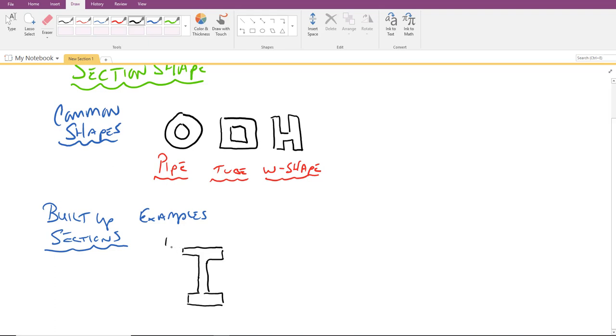So occasionally what they'll have you do is go ahead and weld a piece of steel plate on the top and the bottom, and essentially what you've done is now you've created a strong and weak axis that are nearly identical to each other.